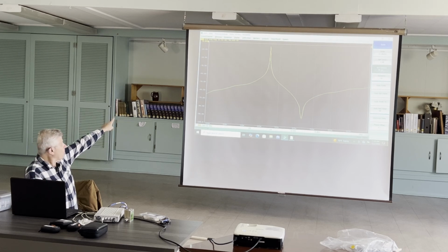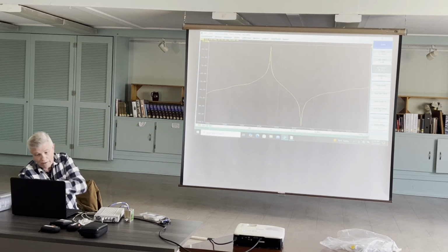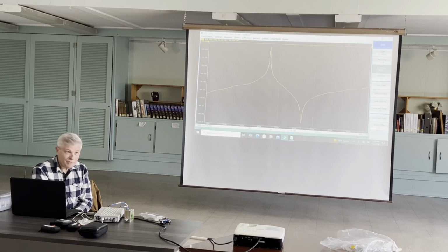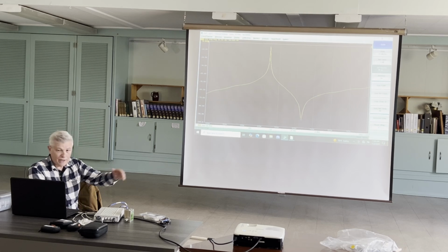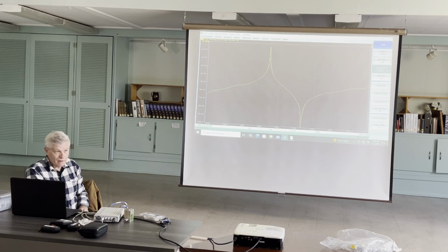And you notice the roll-off is pretty steep. But look at what's going on. You've got a null up there at about 600 and something megahertz. So these are not infinite response filters necessarily. Now, if we really widen this out, we probably see harmonically related peaks from this filter. As a matter of fact, we could do that.